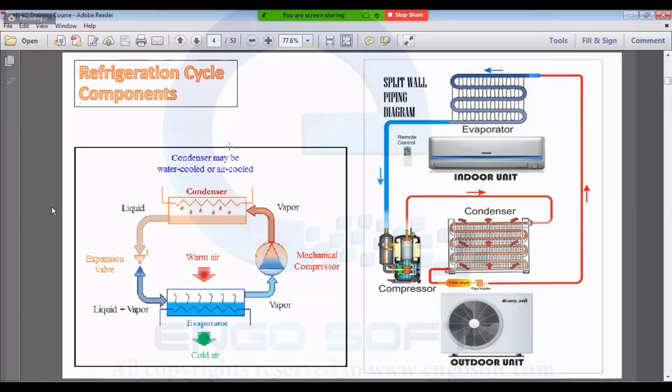This 70 degrees Celsius can reject heat to the outdoors through a condenser by removing heat from the hot freon and releasing it to the hot air, which is at 46. Then it returns to liquid state. For the compression cycle, we need to return the liquid to the cold state. This is the role of the expansion valve. Okay? Okay, the condenser is the outdoor unit.